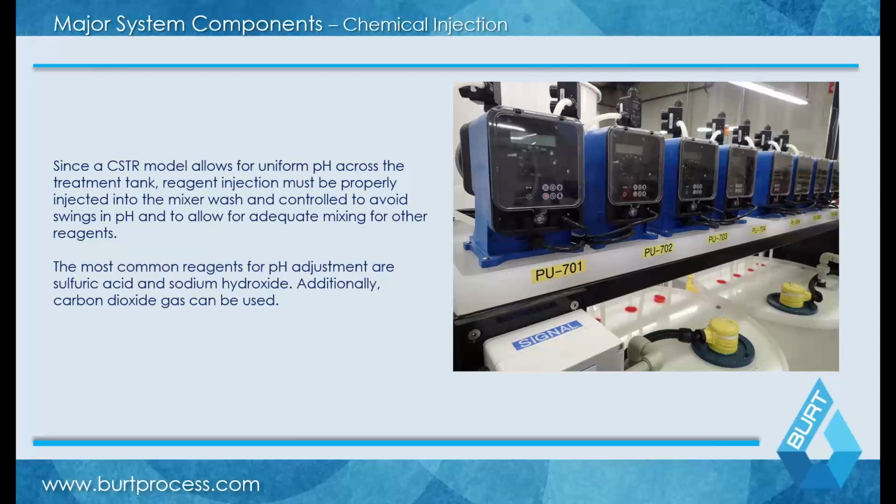Thank you, Michael. One of the things that comes up quite a bit, and you can see in the picture I'm showing here, these are actually chemical drums, which are basically on board of a system. So, in a pH system, you have a tank, you have your reagents, and your chemicals are going to be consumed as your system operates. So do you want to have onboard tanks that you then fill, or do you want to wheel up a drum every time and basically put it in place?